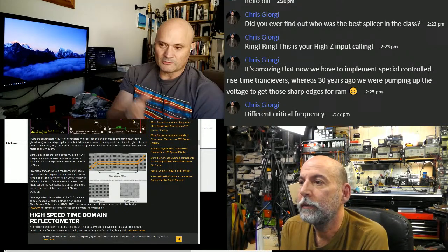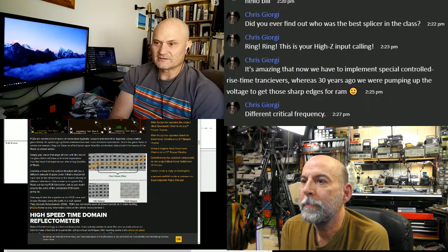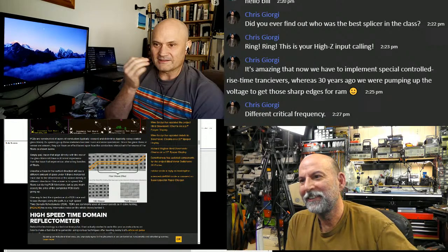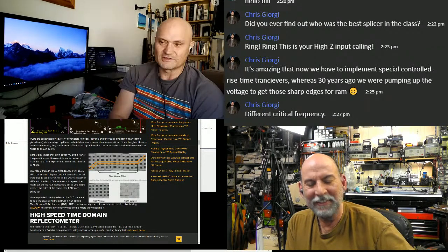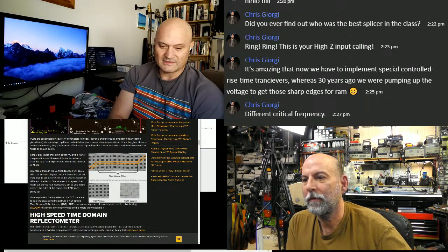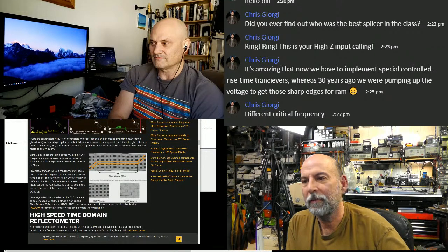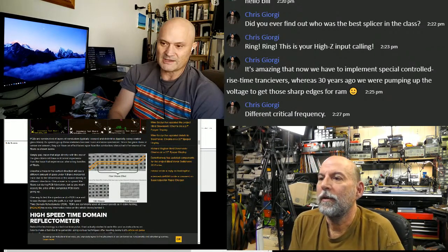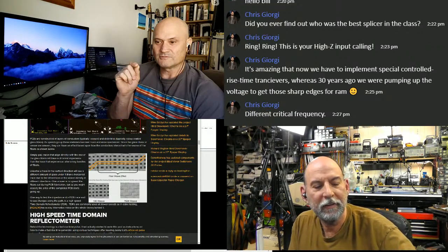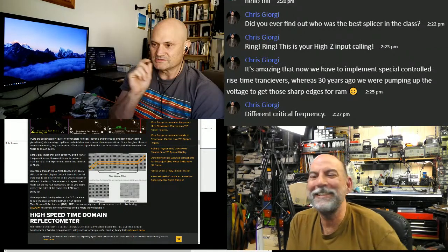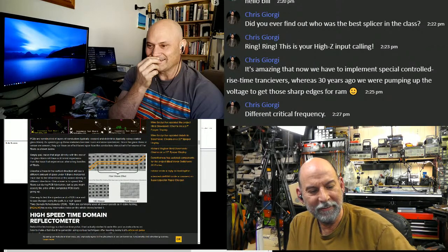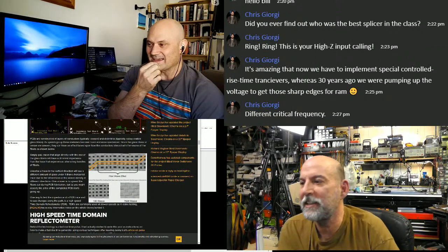We could. It all started back in the 70s with the 7400 transistor logic, TTL. Yes. TTL, transistor to transistor logic, is what that stands for. And they were slow 70s technology. Then late 70s they came out with LS, which stands for low power Schottky transistors. And then advanced Schottky, and then ALS, advanced low power Schottky, and then they came out with all sorts of these. Tons of them now, like ABT, ACTs, yes.